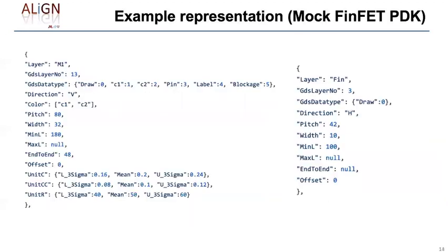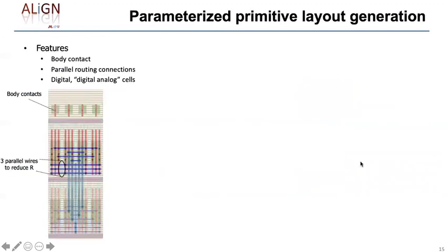Mock FinFET PDK, which is available on our repo, is shown here. So this shows you, for example, metal layer M1 and various characteristics, the pitch, width, etc., associated with this. Similarly, for a fin at the device level, you can have design rules of this sort. Given these design rules, we now create layouts for individual